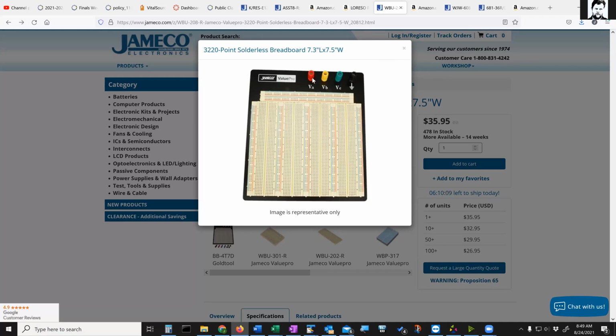When you buy this breadboard, it's going to come with these little connectors loose. Or maybe you can look online to see how to set it up. You want to make sure you set it up so there's the plastic insulator on both sides. I've seen a situation where a student didn't set it up correctly, and basically the metal on this connector was touching the board, and the metal on this connector was also touching the board. So it's just a dead short to each other. You want to avoid that. It comes with a little insulating piece of plastic, and you need to put that on there to actually make this insulate from the board.